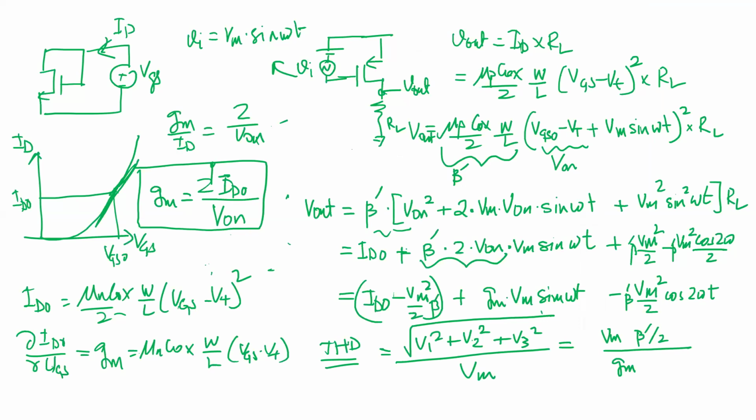Once we make the amplifier high gain and put it in feedback, then the distortion will go down. But with this amplifier, you're not even going to get 1 or 2% for any small signal, even for 1 millivolt. Okay. So, yeah.